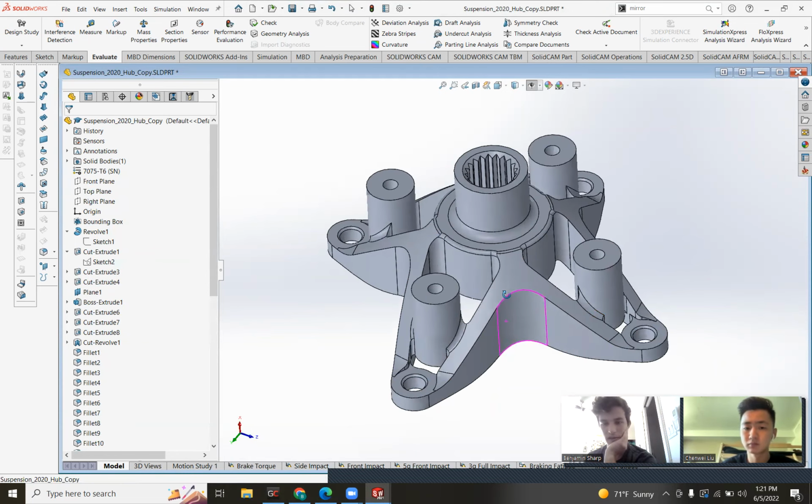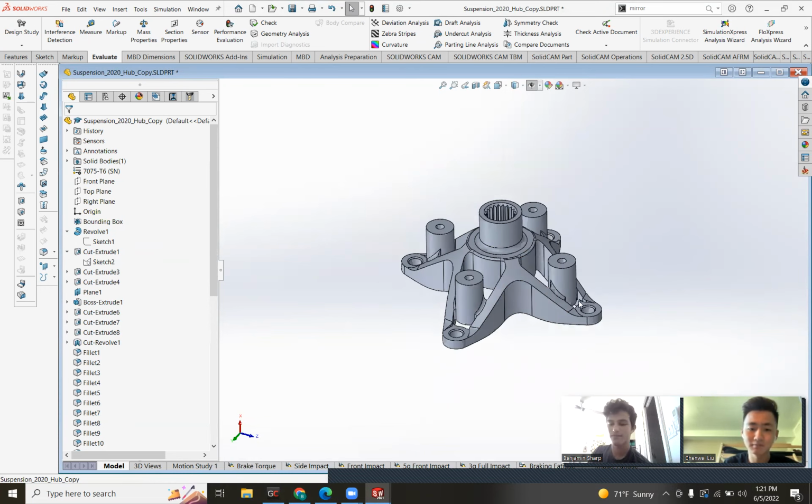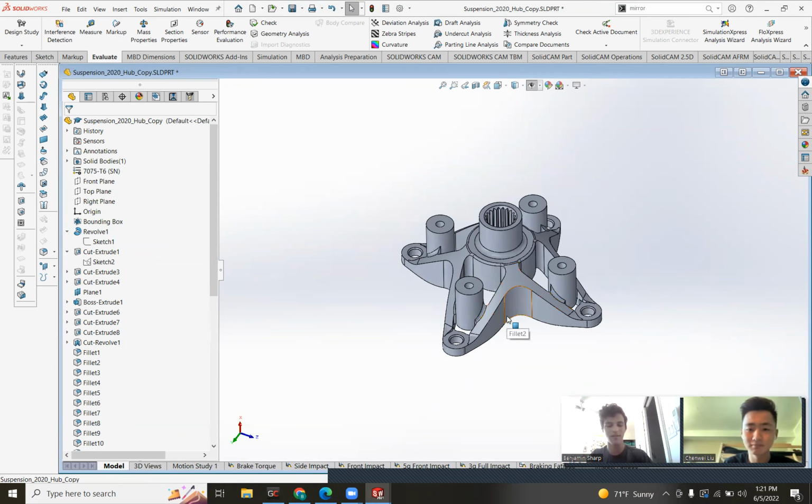You're much better off coming up with really good load validation and FEA for the arms, load validation and FEA for the knuckles, a good goofy arm or a tube to replace it. Spend your time on coilovers, spend your time on carbon fiber tie rods, spend your time on better half shafts that are lighter, that sort of thing. Don't spend your time on a hub. And you already have 4 of them. So yeah, that's what I have to say about this.